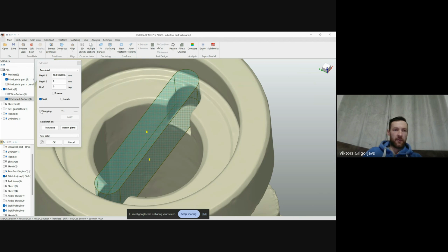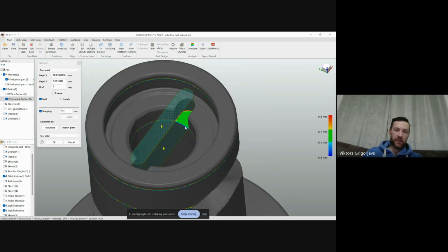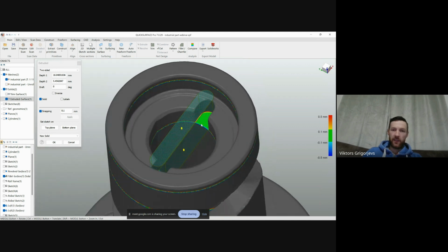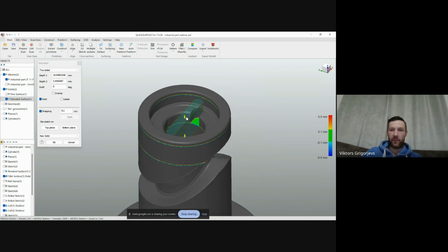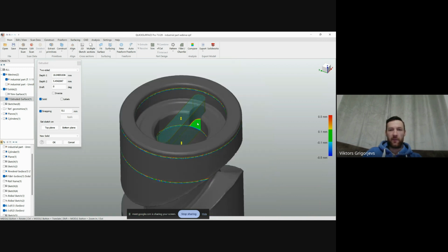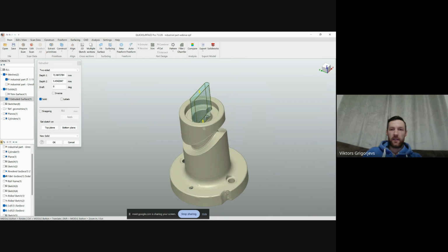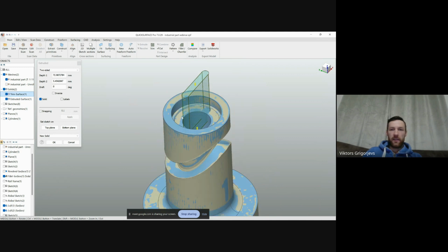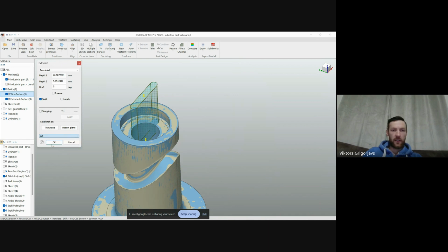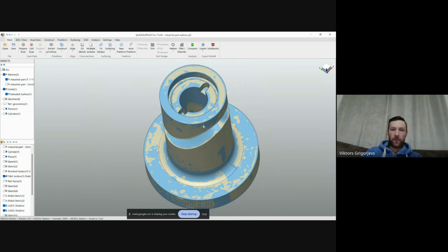Extrude. Again, we have nice tool as snapping. Just hover over, find. Well, as this is quite nice and clean mesh, it's not a big deal to find the perfect spot. Sometimes if you have some more grainy or noisy meshes, you will be able to see how the color map is changing while you're moving this point around. And I just pull it up, bring back our solid, and here choose cut. Perfect.